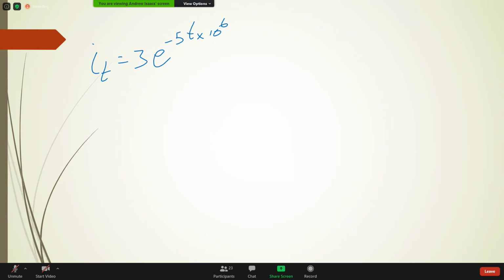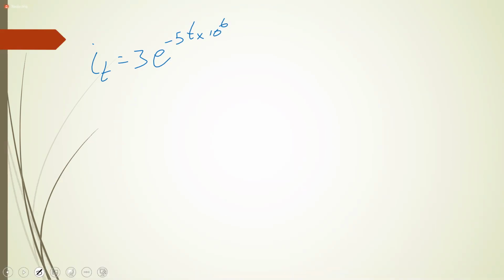We're dividing that current. So it would be this value times the 12 ohm resistor, and then divided by 12 plus 6.